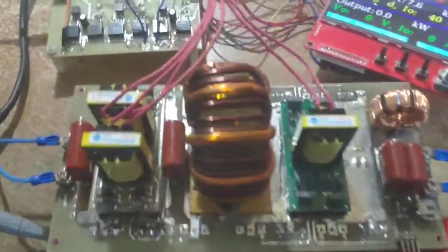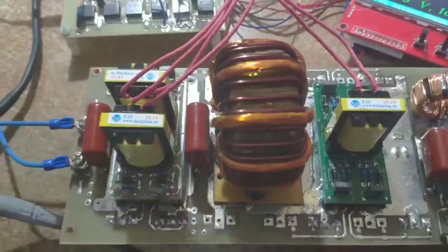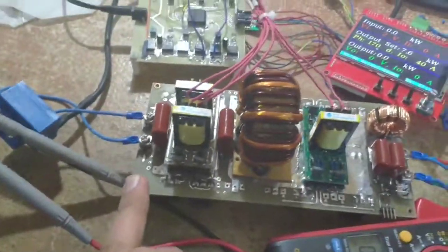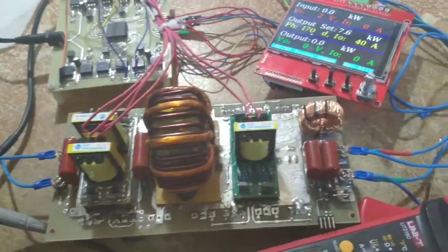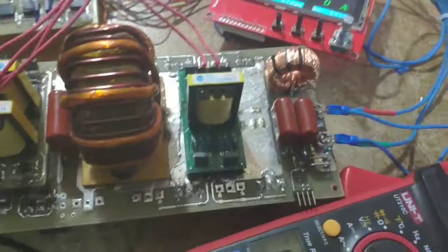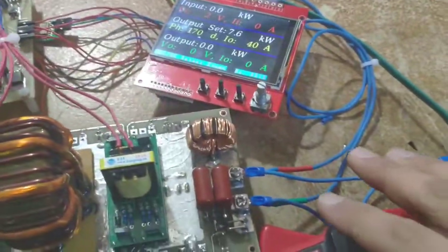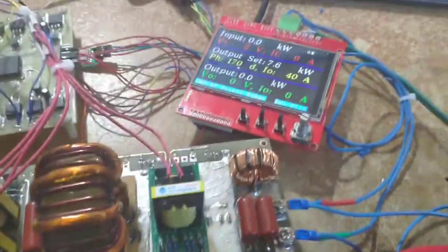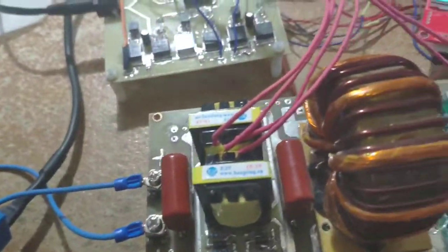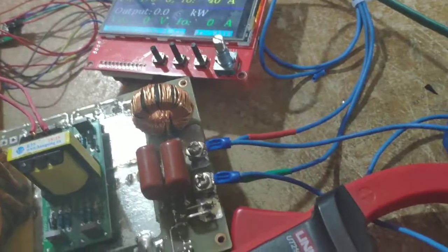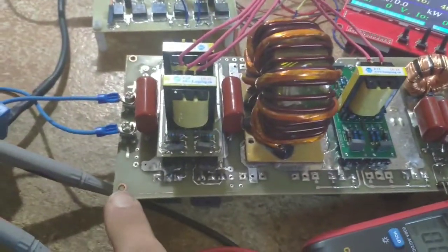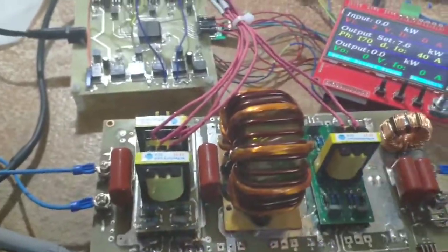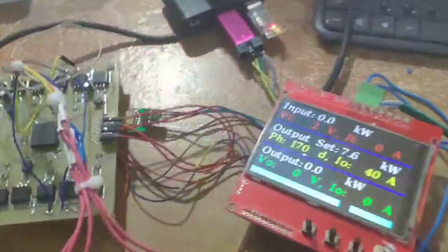Hello everyone, this is my bidirectional converter. It converts the high voltage DC bus to 48 volts to charge batteries and vice versa, which means if the power in the HV bus is absent, the power will flow from batteries, this low voltage, to this high voltage to keep the inverter bus or the high voltage DC bus an uninterruptible power source.